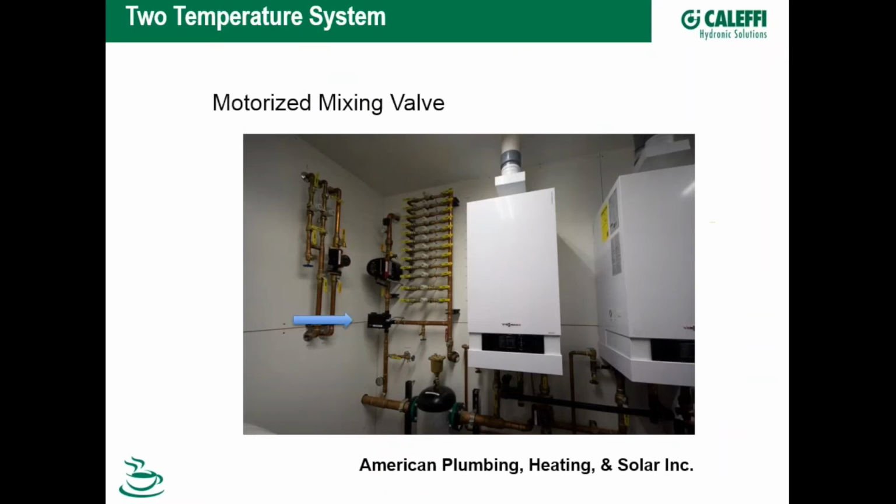Here's a picture showing a motorized mixing valve. You actually have 2 boilers off to one side. Here's the motorized mixing valve here. Hot water comes in here from the boiler. Here's cold water coming back from the supply. And then it's moving up here through the pump.